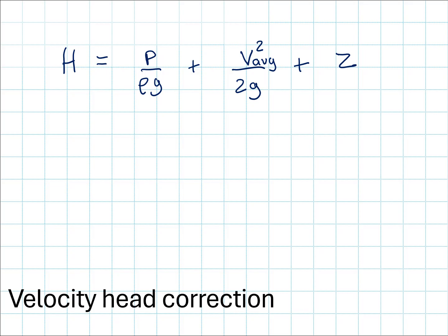But if we calculate based on an average velocity, which we know is an underestimate, and then you'll notice that in calculating kinetic head, we square that slightly underestimated velocity, so it compounds the error, and then we systematically underestimate kinetic head. And this is a problem, right? If we're systematically underestimating the energy of our flows, this can lead to erroneous engineering designs.